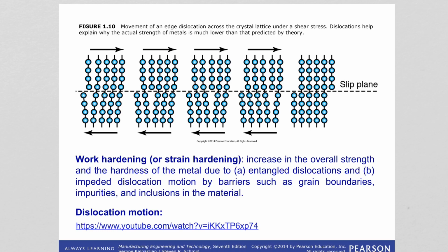So it was figured out that actually there is this line defect in the structure, the extra plane of atoms, right? And that is the one that is moving and breaking the bonds and then reforming the bonds inside the material, okay? And since only a single bond is breaking and a new one is forming at the same time, of course, breaking and forming the bonds, one will require energy, one will generate energy.